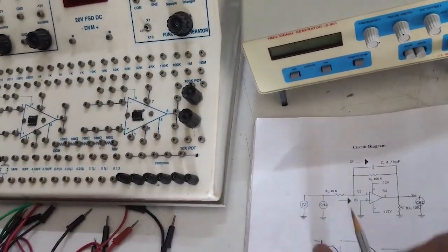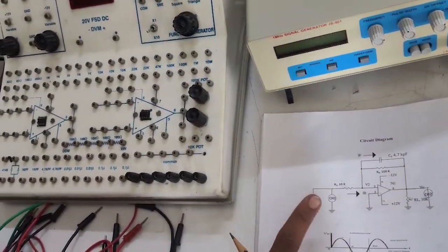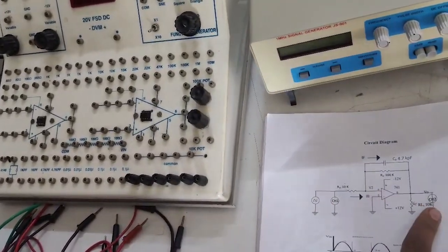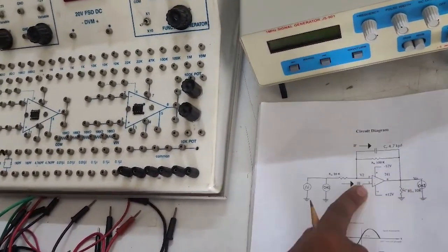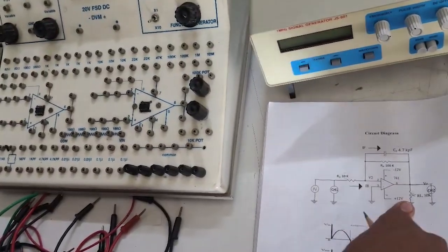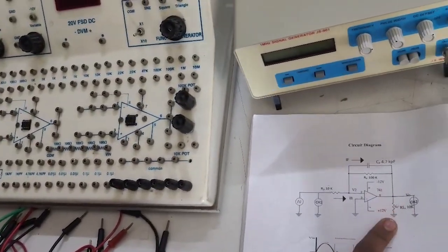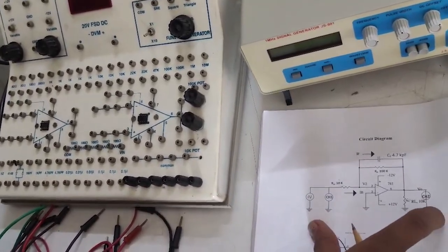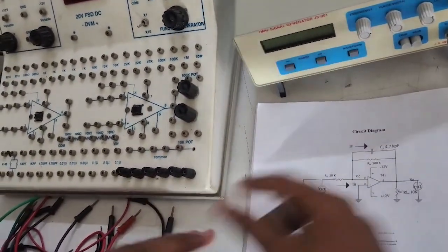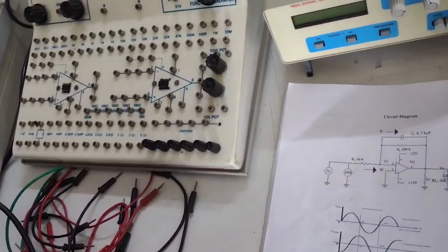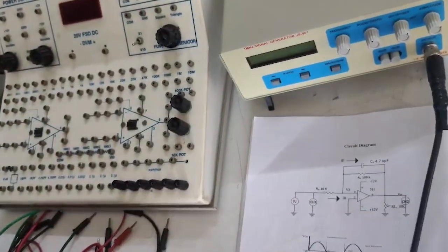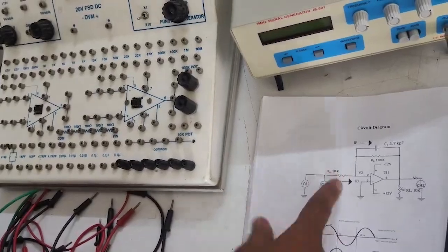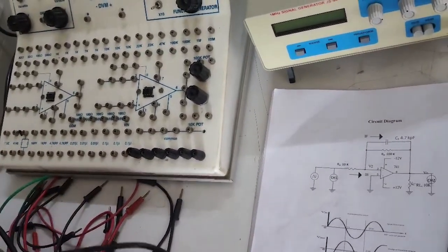So this is the circuit for the experiment. One thing to keep in mind is, your audio oscillator, channel 1, channel 2, pin number 3, and pin number 6, where after the load resistance, are all grounded to the same point. I'll just explain how the circuit goes. First we're going to take the audio oscillator and connect it to the 10 kilo ohms resistance, which is our R1.